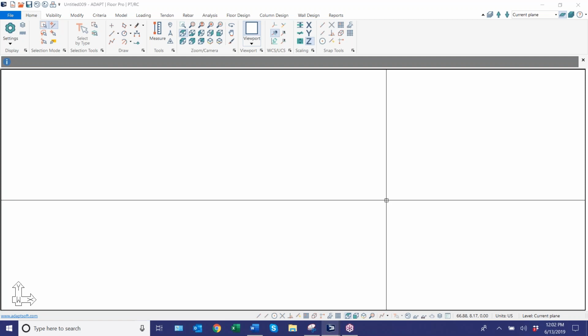You could still obtain FEM analysis results and look at bending moment contours, stress contours, axial stress contours, etc. But all of those are just raw analysis results that you would then have to use to design reinforcement, which would happen outside of the program.